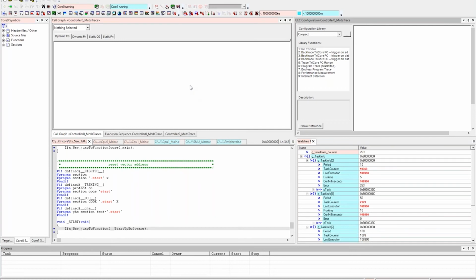If you want to use trace, we have at first to define a so-called trace task that will allow us to observe the execution of the tasks which are run on CoreOne. Best practice is that you start the trace at a specific point in time and record everything after that. Or as an alternative, trace everything between 2 points in time. For example, if you have a fixed period and you assume that within this period something is happening, then you can also trace within 2 points in time.